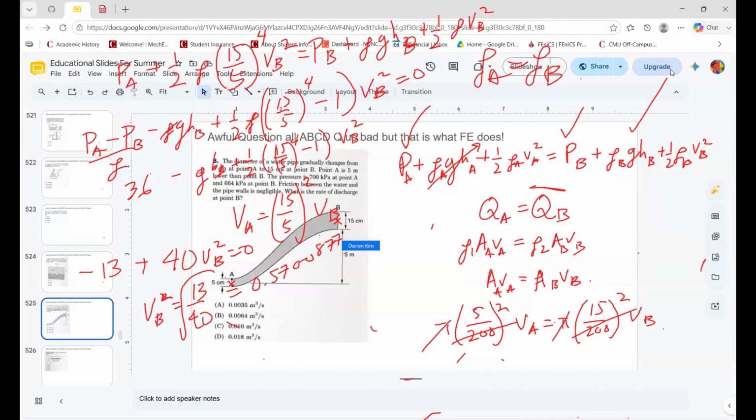0.0877. With that said, what you do now is basically put that back into here because I need the Q rate on the top, right? So whatever I have right now, that's the velocity. So velocity multiplied by the area over there, which is basically, what's the area there? 15 divided by 2, 200 because it is centimeters, and then it's going to be squared multiplied by pi, and then multiplied by 1000, which I don't care too much about, and that should give me the answer.